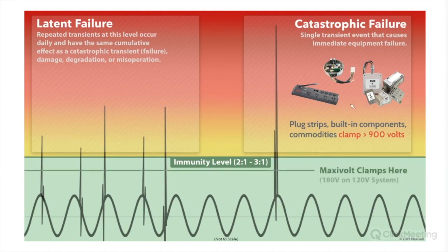Yeah, so I guess, Alan, the point for me with all this is, be careful what you get. SPD X versus SPD Y are different. They have different performance, different characteristics. Spend a little bit of time investigating what you're getting so you understand what kind of protection you're really going to get. And those minor things as far as, okay, an SPD is an SPD, well, that's not quite true. It's like anything else.